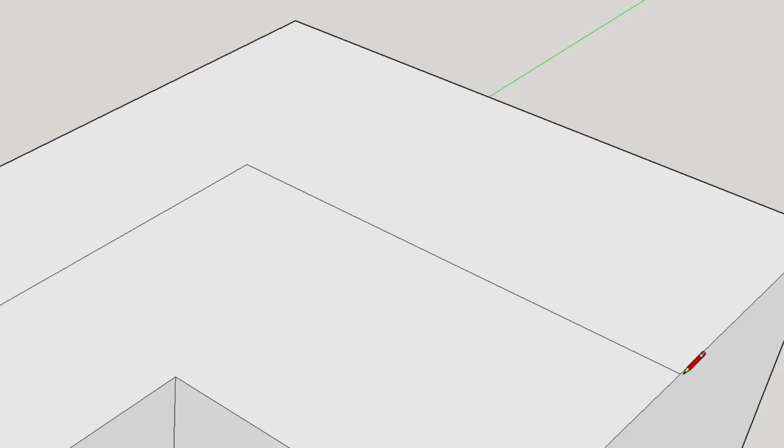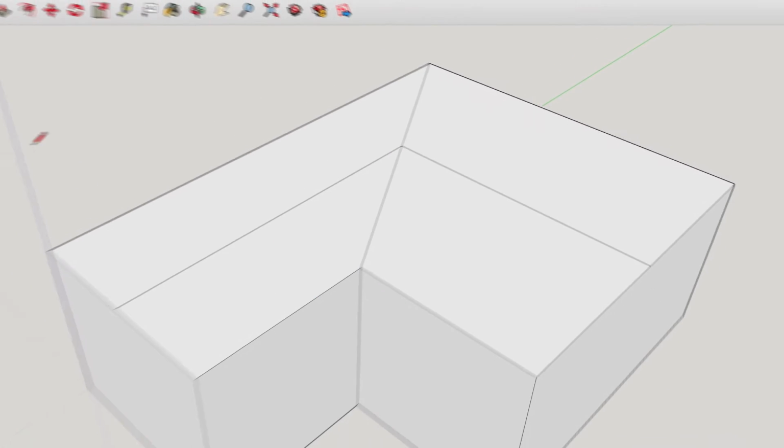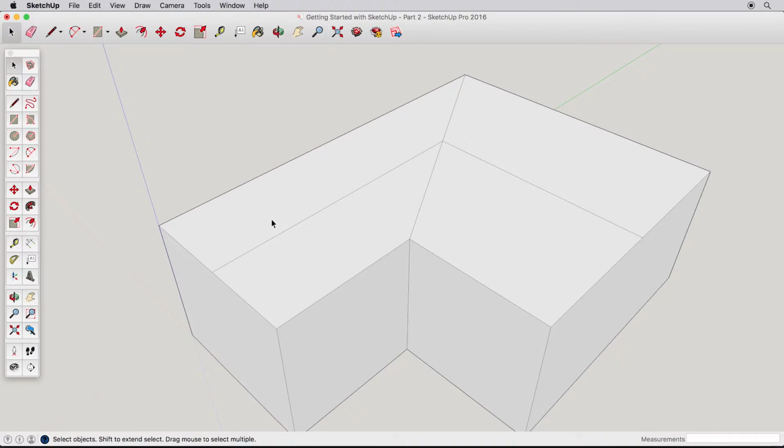Now that we have both ridges in place, simply draw the line where the roof will fold when we move the ridge lines. Use the Select arrow and click on one of the ridges. Then, hold the Shift key and watch the icon. There is now a plus-minus that indicates that you can add to, or subtract from, your current selection. This allows you to select other entities and deselect them as well while holding Shift.